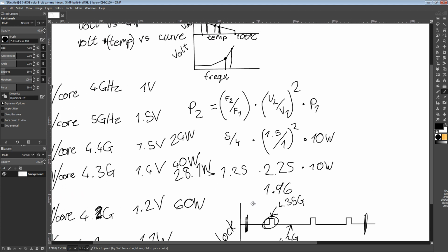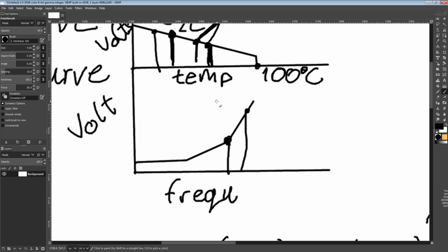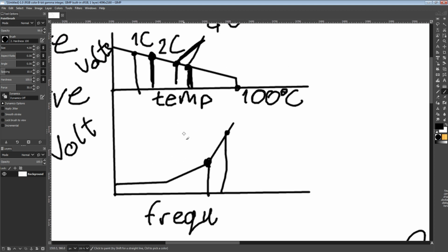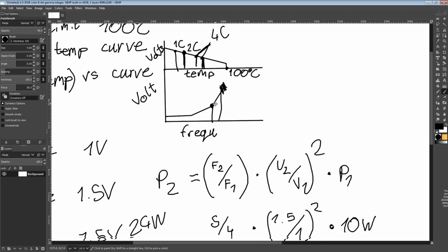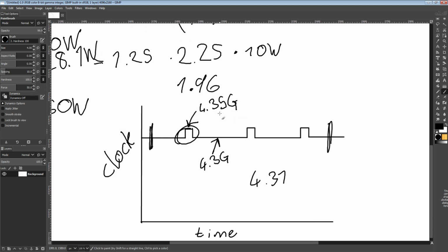I really wish AMD gave us access to whatever frequency voltage relationship settings they have on their CPUs, because personally, if I was messing with overclocking Ryzens, I would just cut that end off. The thing is, it's easier to stress test a frequency that's actually constant. These spikes last literally a couple milliseconds, just long enough to crash the CPU, but not long enough to make any difference in terms of performance, especially because it's only like 50 megahertz more frequency.